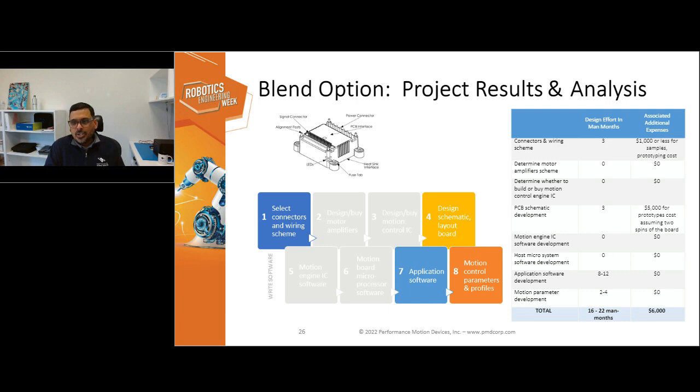This has all the controls. It has a host processor, and you're just doing a simple passive card with the right set of connectors for all the things you have. So you have the power, you have host communication connection, you have motor connection and encoder connections, and any other sensors that you have. So that's all the card is, just the passive connectors you want.